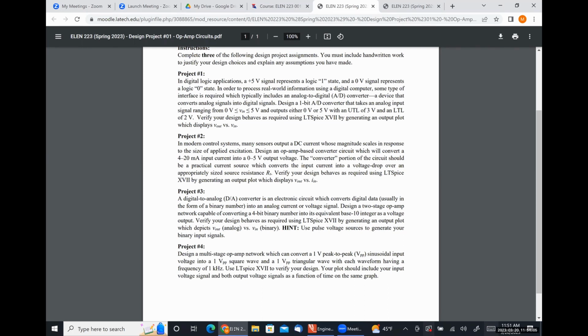Then we want to take the output from our comparator and generate a triangular wave. So actually this would wind up using an integrator, not a differentiator, because the integral of a square wave should be a triangular wave. But what we need to think about is the fact that we have energy storage elements, particularly capacitors, that take a certain amount of time to charge and discharge, right?